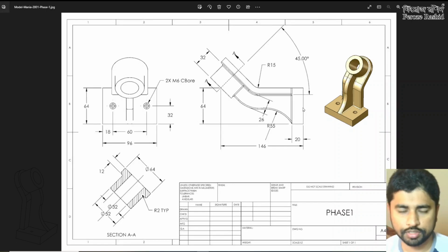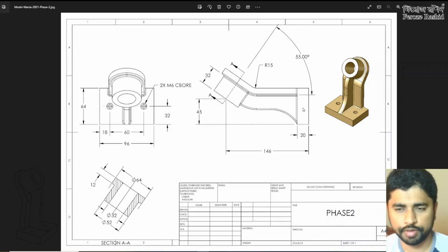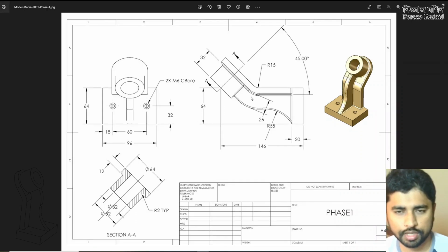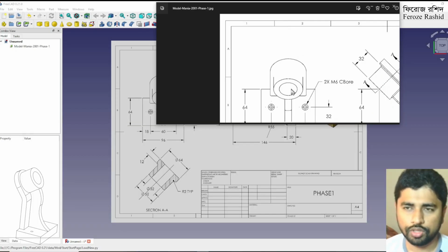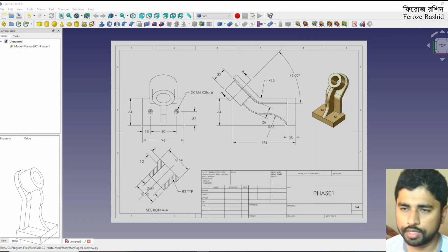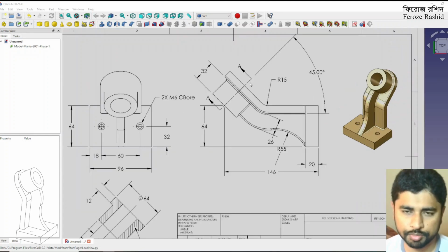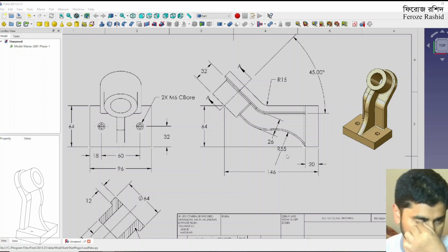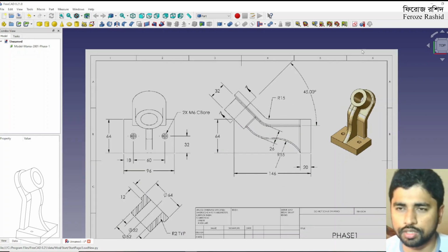And it is easy to build phase 1, pretty easy, a 5 minutes job. And then when it comes to phase 2, the model breaks down. I've been struggling to do this transition and found out that dependency between two sketches is the main reason for the model breaking down. So I think making them independent, with a minimum number of dependencies between two sketches, is the key to solve this problem. So let's get started.